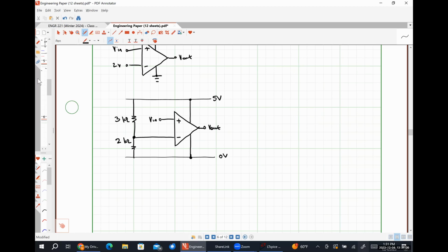So I think one big issue is that you don't have these grounded, and so it doesn't know what it's putting them with respect to. There we go. That's our reference. This is a non-inverting, right? Because your input is on the non-inverting terminal and your reference is on the inverting. Yeah, that's right. So if you swap those two voltages, then it'd be high, then switch to low.